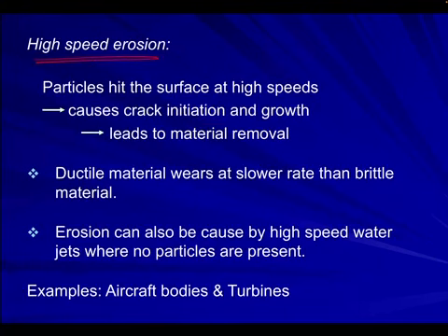So the particles hit the surface at high speeds, causing crack initiation and growth, and leading to material removal. The ductile material wears at a slower rate than brittle materials. That's quite important. So your ductile material is actually better than your brittle.